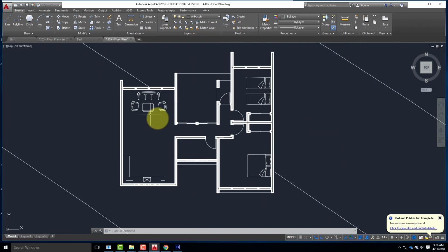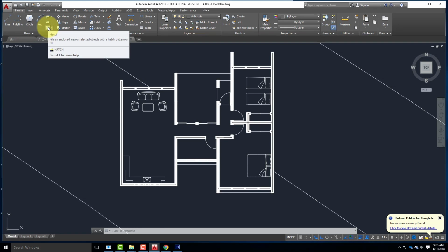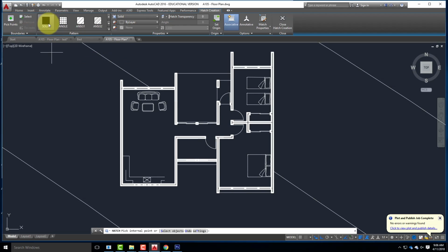I've filled in those. Now maybe I want to put some hatch or some parallel lines that represent a floor. So for example, on the little handout here, I have tiles on the floor in one place, and I have kind of a wood grain pattern on the floor. I can do the same thing here. I can use the hatch command to do it, so I'll click on the hatch button. And instead, on my pattern, I'm going to start with just a set of horizontal lines.